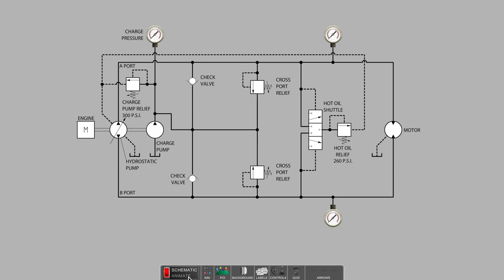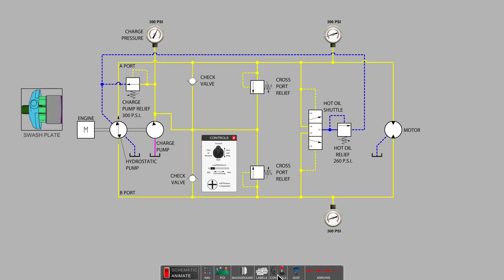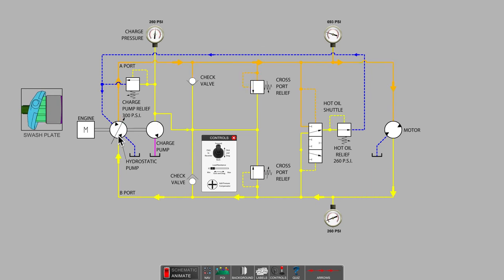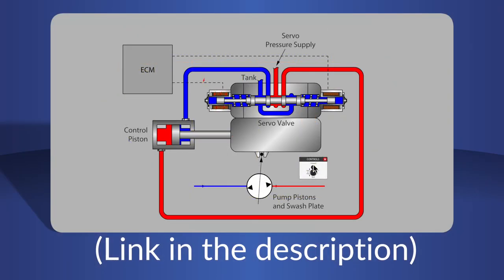This will be part 1 on closed-loop hydraulic systems, sometimes known as hydrostatic drives. Let's get right into the functional features of this type of hydraulic system. Instead of a directional control valve to change the direction of rotation of the hydraulic motor, and instead of a variable orifice for changing the speed of the motor, a hydrostatic drive uses a displacement controller, or stroker, attached to the piston pump's swash plate. The basic function of the displacement controller was covered in a previous video.